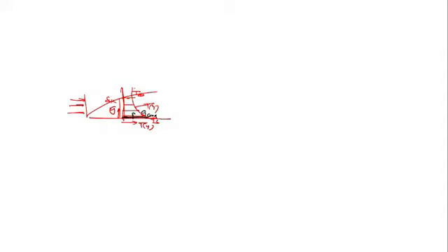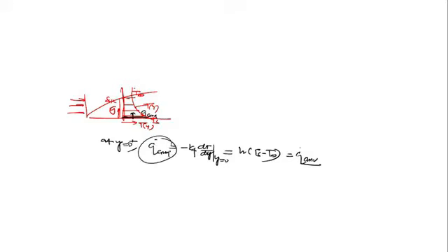And in the rest of the fluid, at the wall, at y equal to 0, the Q conduction is equal to minus Kf into dT upon dy at y equal to 0. This is the temperature gradient at y equal to 0. This should be equal to what? In the rest of the fluid, it is by convection, h into Ts minus T infinity. Yes or no? Tell me please. Q conduction equals Q convection. But this is the conduction at the wall, and this is the convection in the rest of the fluid.